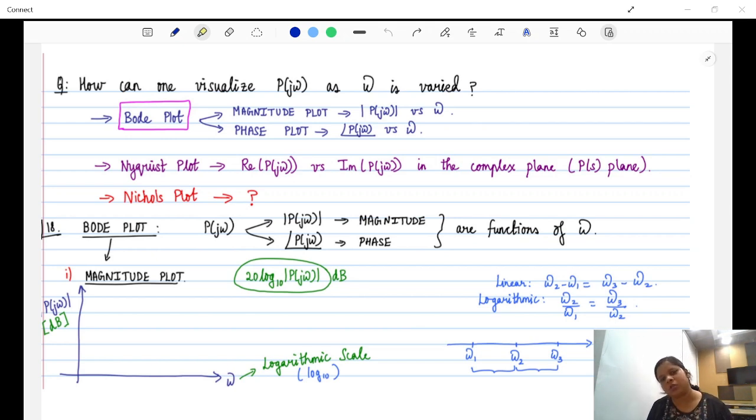That okay, if my root locus goes in the right of the S plane, or my closed loop poles always remain in the right of the S plane for any value of k, then the system is unstable, right? In the Routh-Hurwitz also, you said that if there is any sign change, that means the poles are going to lie in the right half of the S plane. Hence, my system is unstable.